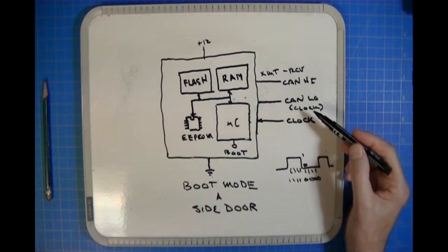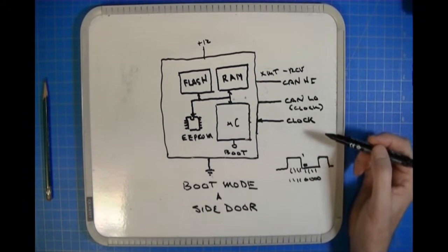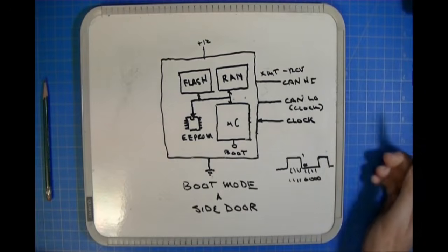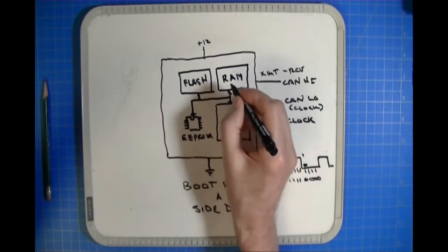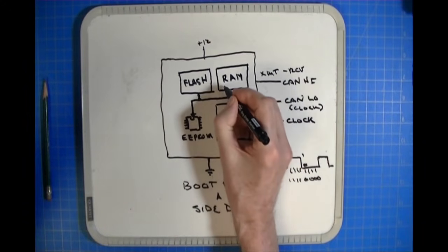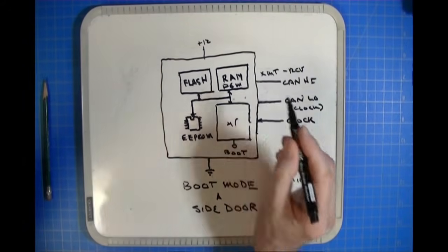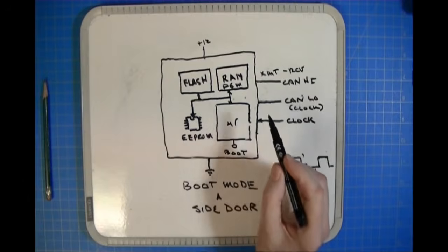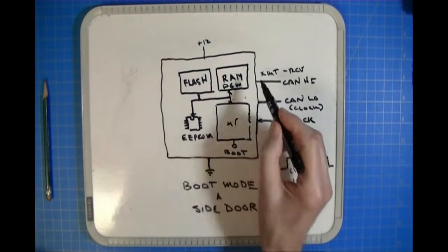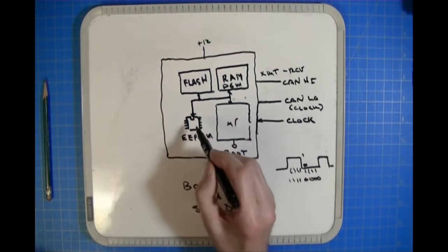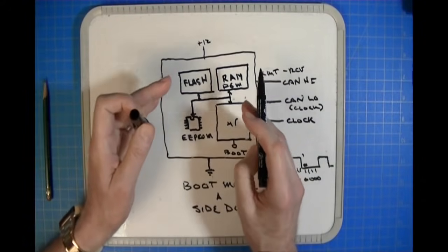But the whole purpose of boot mode is to allow a program to be uploaded from the tool into RAM, okay? So the RAM is now going to contain a program, BDM, okay? And the purpose of that program is to, once again, read and write flash, manipulate bits on the module, access the EEPROM, whatever, okay? But it's a separate program which runs in RAM, all right?